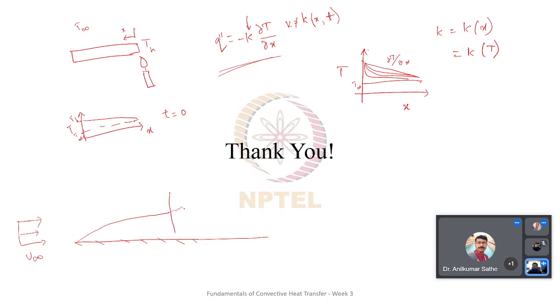Then comes a region where a transition occurs. So here the flow keeps switching between laminar and turbulent, and finally it becomes fully turbulent. And within that turbulent zone also there is a sub layer which is laminar. But we restrict our discussions up until here, the laminar one.